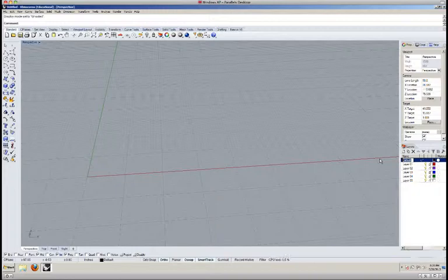The next thing I'm going to want to do is set up my layers, because I remember that layer management is really important, and it will be the way of defining all of the different elements for the project. So we've got rooms, and remember, just double click on the layer name to be able to change the name. Connectors, we've got enclosure, and I'm just going off of the handout in terms of what the names are going to be.